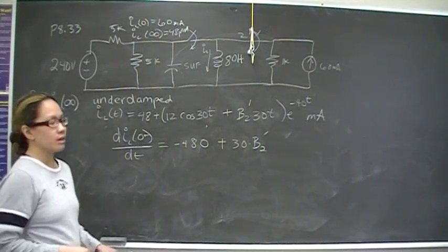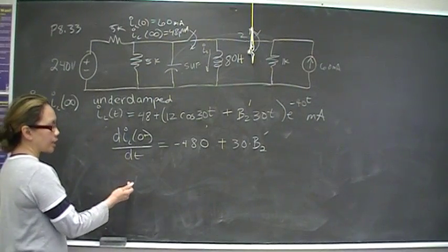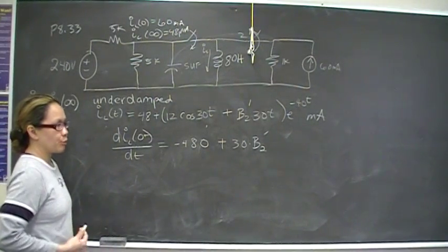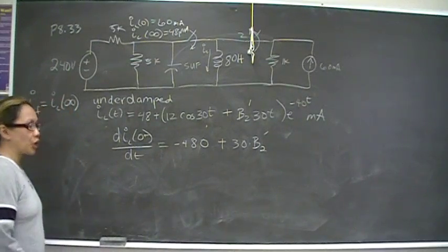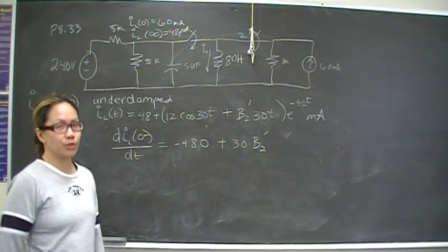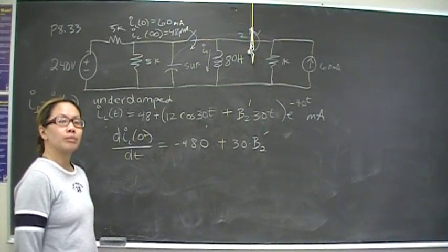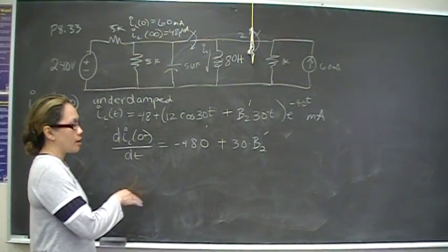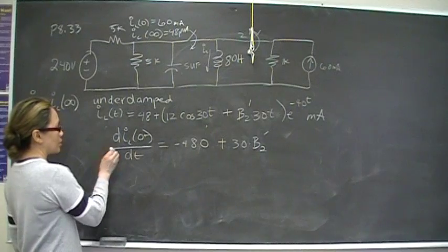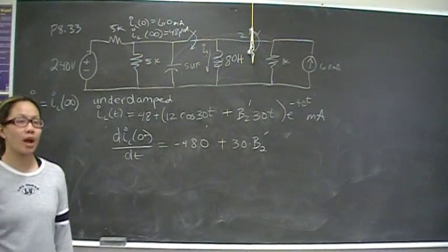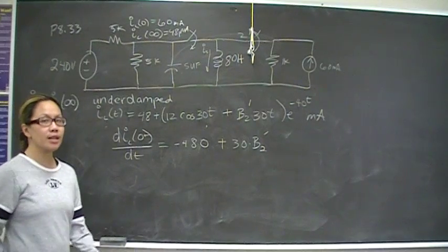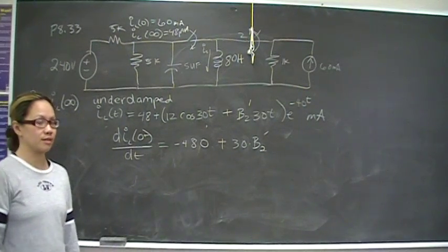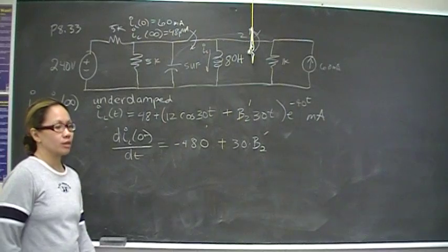When you see current through the inductor, it's pretty possible to say, well, current can't change instantaneously through an inductor, so this has to be 0. So then you set this equation to 0. The reason why that's wrong is because it's true that current can't change instantaneously, but it can change voltage instantaneously. And the same vice versa.